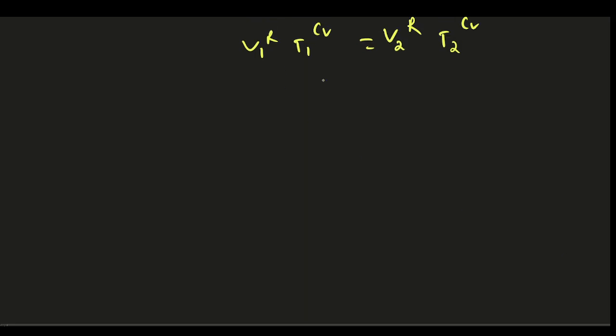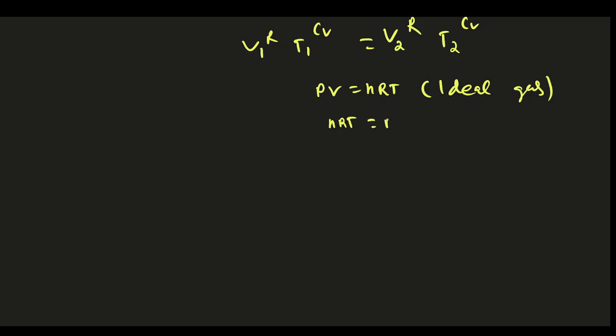so temperature we do not need, so what we will do, again we will put PB equal to nRT, the ideal gas formula. This is for the ideal gas equation. We are doing the reversible adiabatic process for ideal gas equations, so that's why we are using the ideal gas formula repeatedly. So PB equal to nRT, so nRT equal to PB, so I can say that T equal to PB by nR. So I will put this T value here.